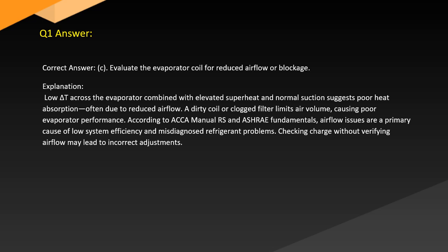According to HVACR manuals and ASHRAE fundamentals, airflow issues are a primary cause of low system efficiency and misdiagnosed refrigerant problems. Checking charge without verifying airflow may lead to incorrect adjustments.